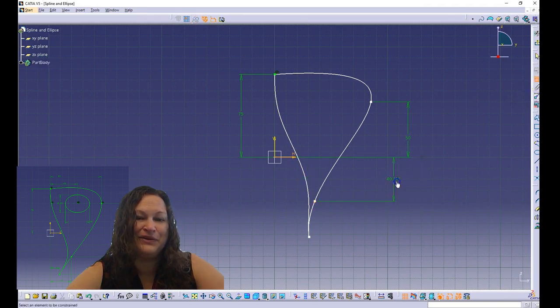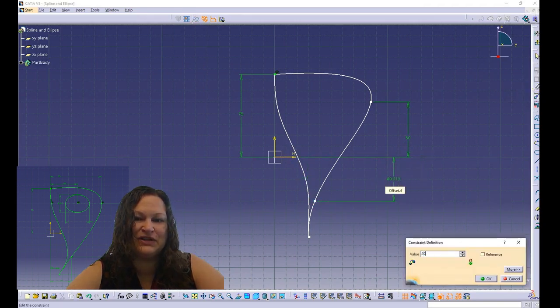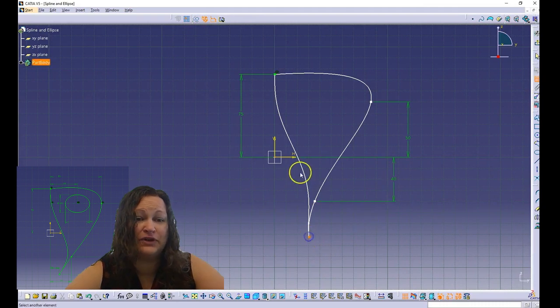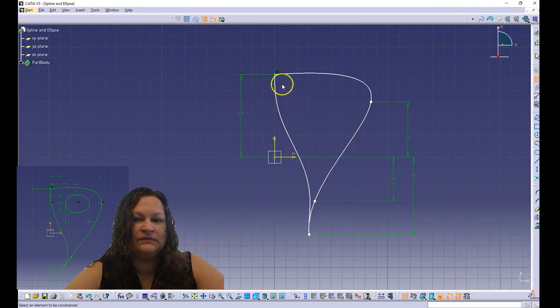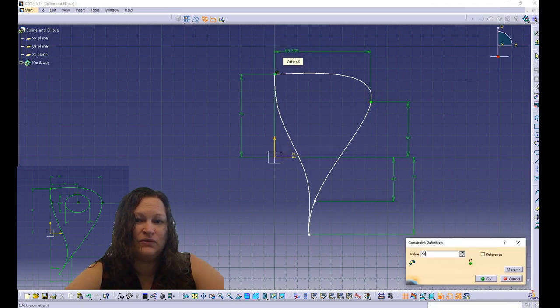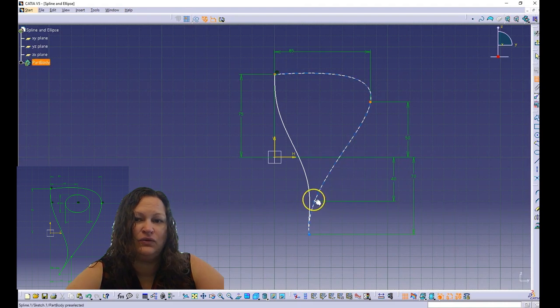This is the worst part about using a spline: the more anchor points you use, the more constraints you have to then add. So it is easier if you go ahead and double click into your constraint tool to activate it and hold that.